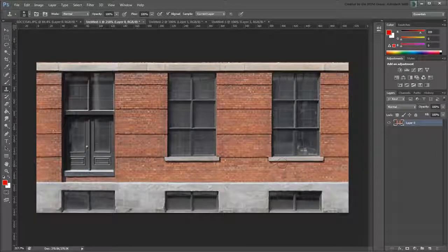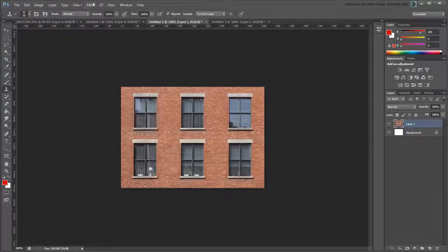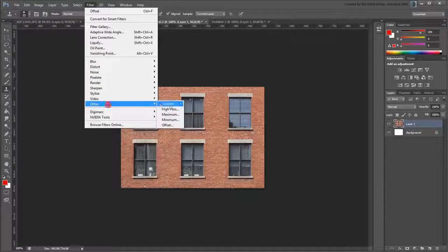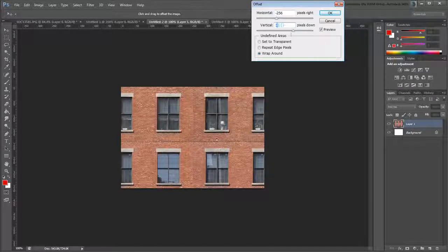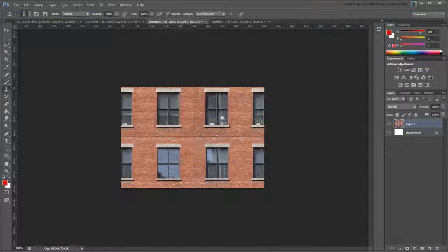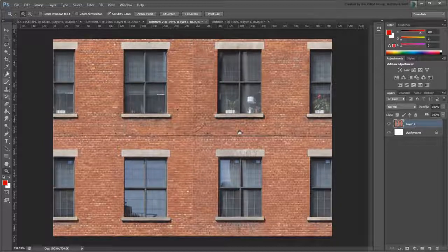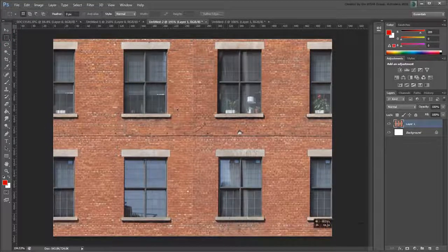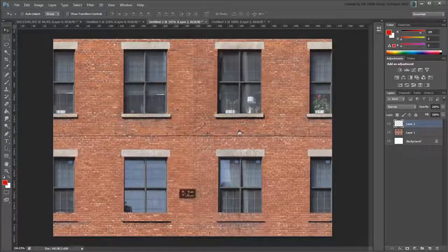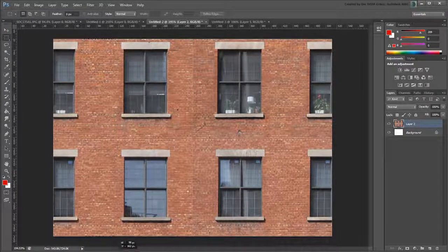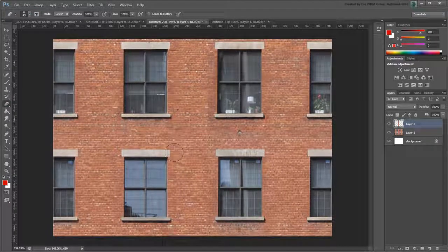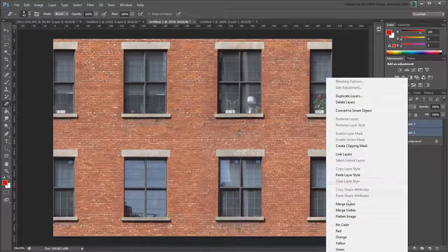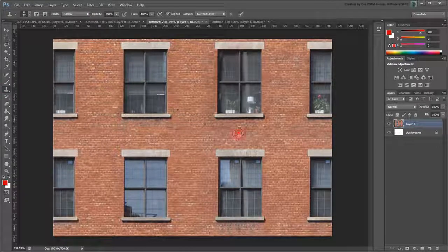In the case of a texture that needs to be tiled horizontally and vertically, such as a typical floor for example, then you need a two-direction offset. As you did before, clone other areas to fix tiling seams. And offset back the image after you flatten the layers.